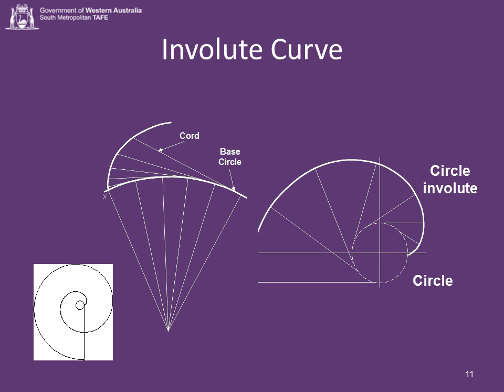You attach a string to a point on a curve. Extend the string so that it is tangent to the curve at the point of attachment. Then wind the string up, or unwind it, keeping it always taut. The locus of points traced out by the end of the string is called the involute of the original curve, and the original curve is called the evolute of the involute. The process is illustrated above. Here it is again.